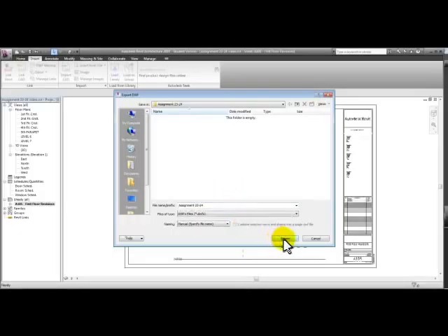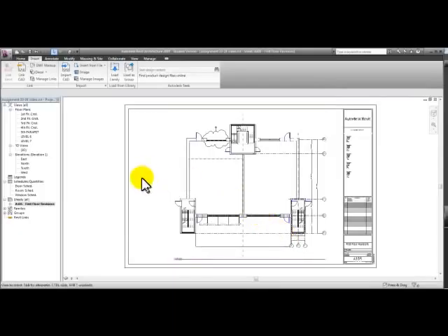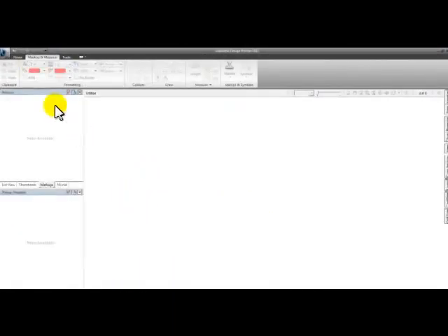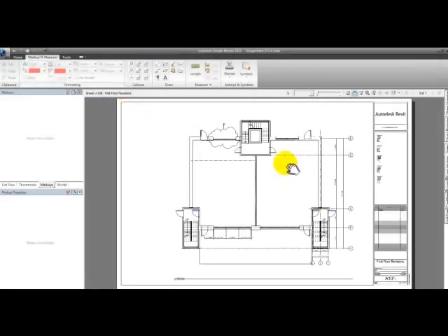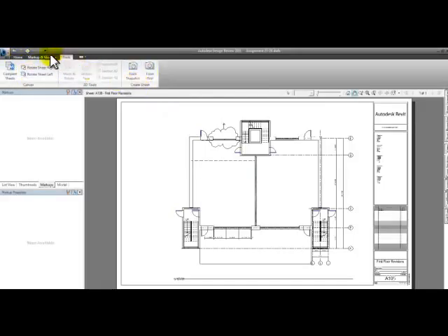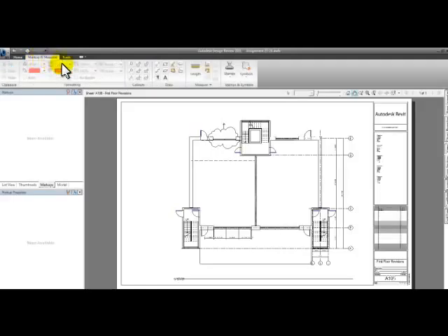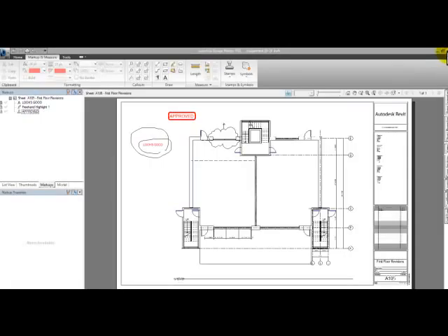Pick Export, and then in the Design Review, a person without Revit or knowledge of Revit can open the exported DWF and use common tools like text box and sketching with a little pencil icon to place information on that sheet, saving the changes in the Autodesk Design Review and closing out of that software.